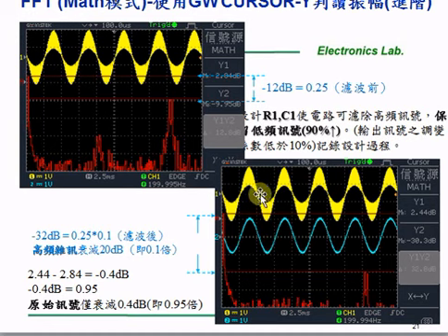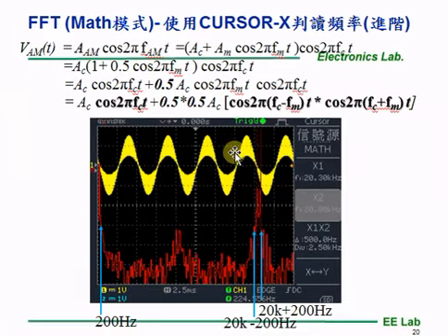The FFT function will generate a figure that represents the strength of different frequencies in one signal. Take our generated noisy signal, for example. We could calculate from the AM modulation formula and see that we will get 3 different frequencies within the AM modulated signal.